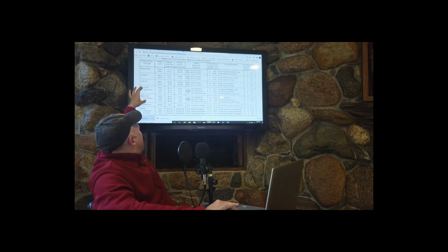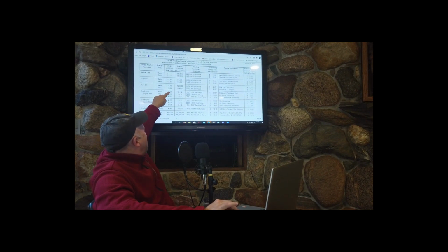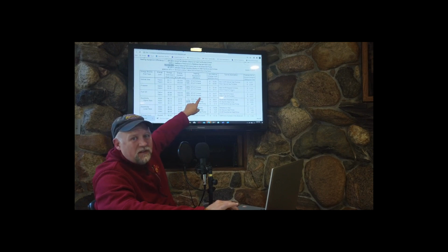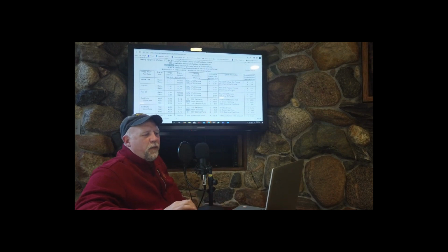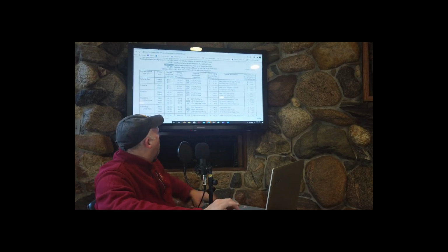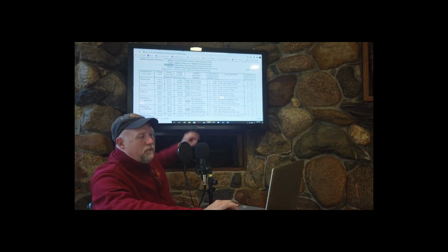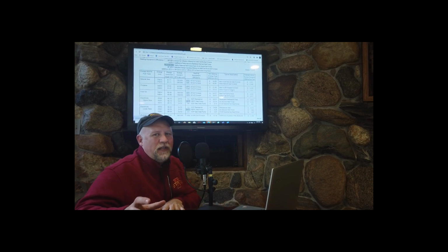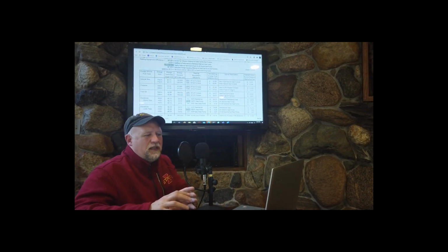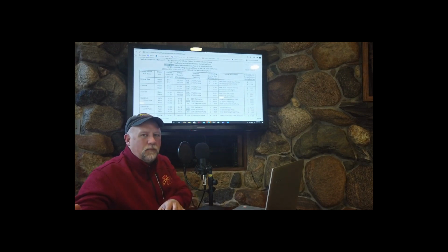I want to get into the electricity. All right, electricity, 10 cents a kilowatt hour, 5 cents a kilowatt hour. Here, if we look at this, one coefficient of performance resistance electric heater. A coefficient of performance of 1. This is another term kind of like EER. Coefficient of performance of 1 means for every kilowatt of electricity I consume, I transfer 1 kilowatt of electricity into our living space. I said, wait a minute, that's 100% efficient.